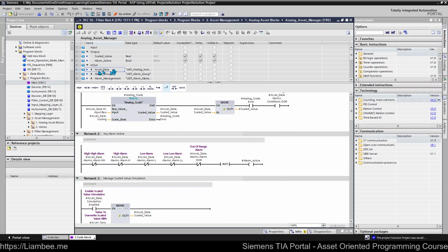So it takes in our asset data and then applies all of the logic that we require against that asset. At this point, we've already been through our input mapping layer. We already have all of our raw values. They will be sat on IO input raw here. We've already taken that in from our hardware through our input mapping layer and/or simulation.